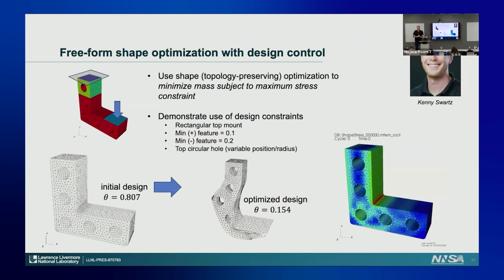All right. So another application is freeform shape optimization. Like I mentioned, a big application is changing nodal coordinates, and you want to optimize the shape of a design. It's similar to the talk from this morning. In this case, this is an application where you want to, say, minimize the mass, make the lightest thing possible, but you don't want it to exceed some stress criteria.